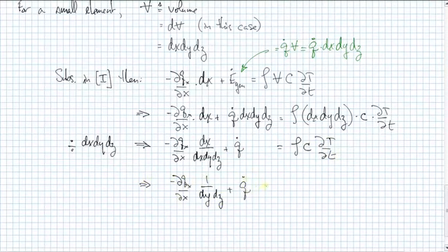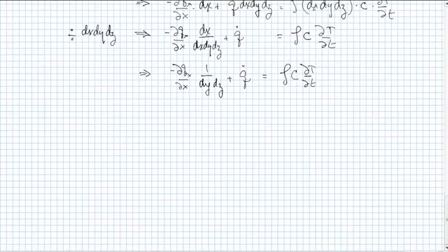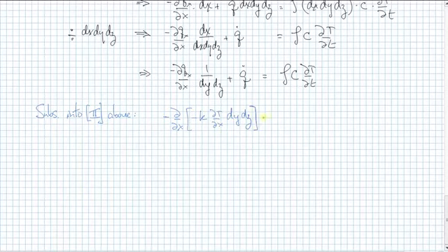Now it's time to substitute Fourier's law, equation 2, in there. I'm going to get rid of that Q sub x. Can't do anything with Q dot because that's a heat generation term, so that's going to have to stay with us for a while.